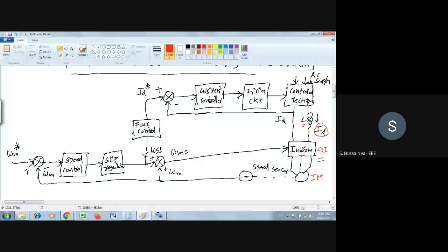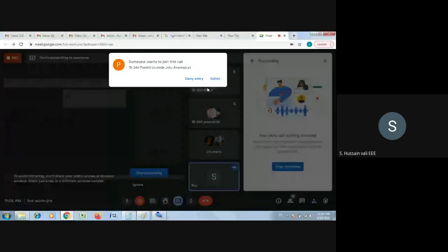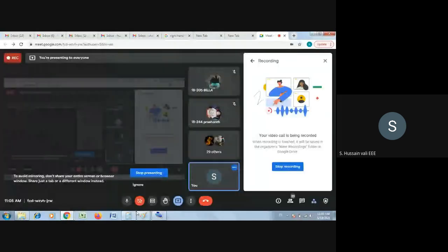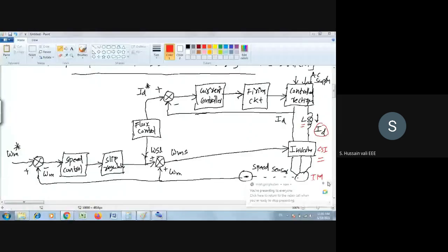First of all, these inverters are there, so you need the firing pulse to the inverter. How you are getting the firing pulse here is that you are getting the firing pulse from this part. Okay, we will see what is that part later also. Then this is a control rectifier. Control rectifier in the sense the rectifier having thyristors. It's not a bridge rectifier. It's a thyristor rectifier. Then for the thyristor rectifier you require the firing circuit. It's important.